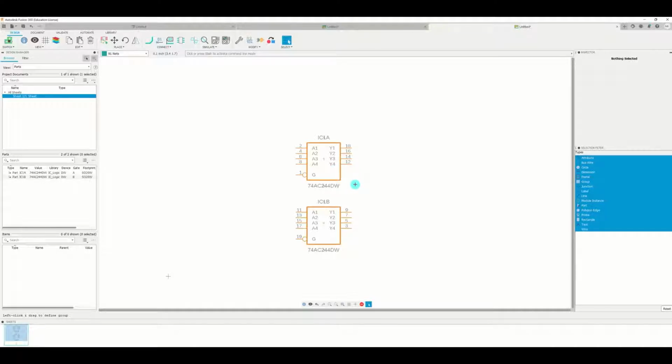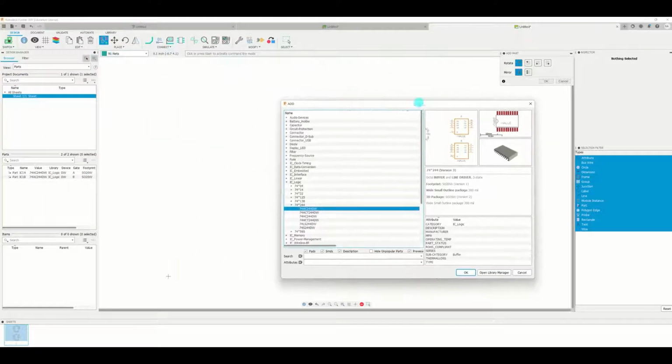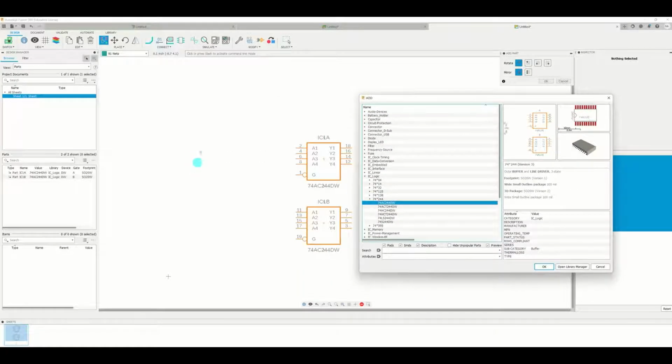Now the next thing to do is we put in our signals. The signals can be connectors or labels, or we can actually place symbols here. Okay, so let's see. Click this again. Now what we have to do is connect pins for this one. If you use a connector like this, that means those are ports, but later on you have to connect the ports to an actual pin. So it's better that we make use of the pins so that you can use it for your design.